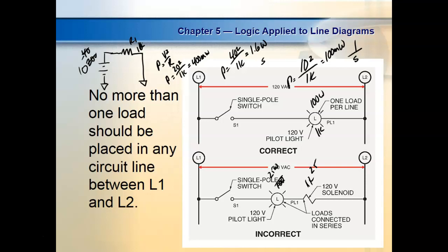You understand? Relays are not going to come in. And the lights are getting current through them, but they're not producing enough work to do the load. So if I come over here and I put 2 loads in series, neither load's going to work because they're not getting enough power to do the work they need to do, right? You understand? So this is why we never have series circuits in motor control.